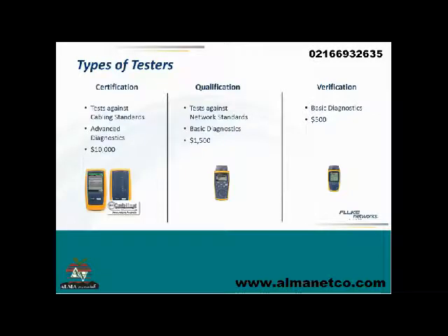At the top of the pile are the certification testers. They test against the cabling standards. And remember that big list of stuff I showed you that you have to measure? They measure all of that stuff and tell you whether or not all of those things pass as per the TIA or ISO limits. They also feature some really advanced diagnostics. To be honest, unless you test a ton of cable, you might not ever run into some of the problems they solve. And they start at around $10,000, so they're definitely a different kind of tool.